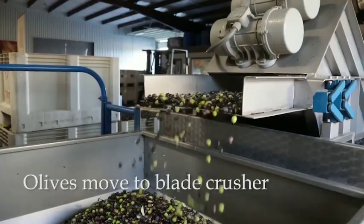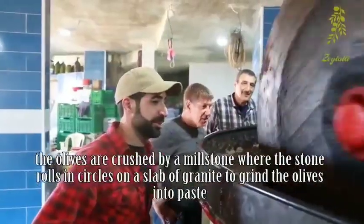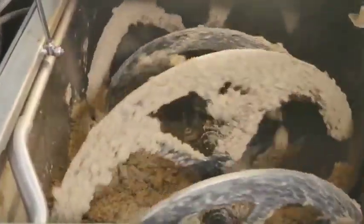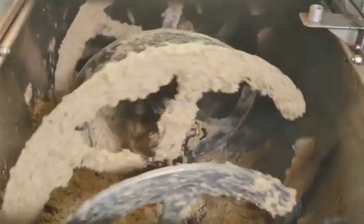So the first step to extract olive oil is to clean the olives. Then crush the olives into paste. The purpose of crushing is to tear the cells to facilitate the release of oil. Then mix the paste for about 20 to 45 minutes to allow the small oil droplets to combine into bigger ones. The paste can be heated or water added during the process to increase the yield.